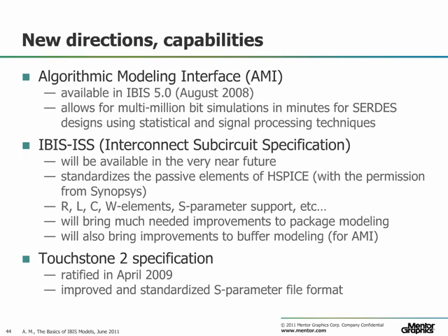The IBIS Open Forum is about to release a new specification called the IBIS Interconnect Subcircuit Specification. The IBIS ISS specification standardizes all the passive elements of HSpice with the permission from Synopsys. Together with the Touchstone 2 specification, which is also the result of the IBIS Open Forum efforts, these new capabilities will bring much needed improvements to package and buffer modeling in IBIS.